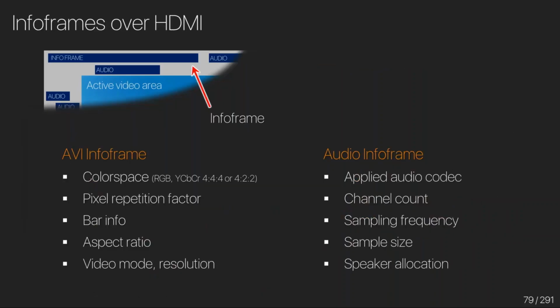So if we talk about the info frames, with each full frame, you're sending one info frame. And why do we need info frames? Well, with DVI, it was more simple. The display device knew what the signal was going to be. It was going to be an RGB signal. But now, because we've got different color spaces, we need to be able to tell the display device about the incoming signal. So with DVI, we had communication from the display going to the source device through the EDID. Now with HDMI, we also have information from the source going to the display about the incoming signal.